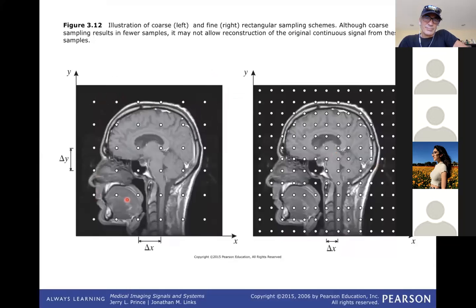Sampling in 2 dimensions, as we just saw here, we characterize mathematically with a sampling rate, or basically a sampling period. If I'm sampling in the x direction at a specific rate or period, delta x, I can visualize it like this, and delta y, like this. You can see we're dramatically undersampled if all we took from this sample were these points. We change our sampling rate by changing this value of delta x, which is the separation between the sample points, the sampling cone.